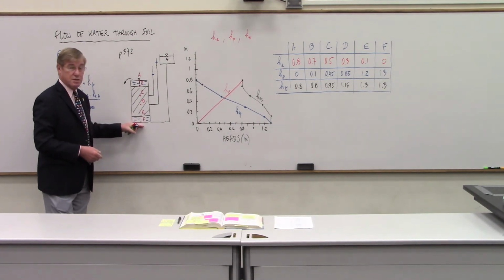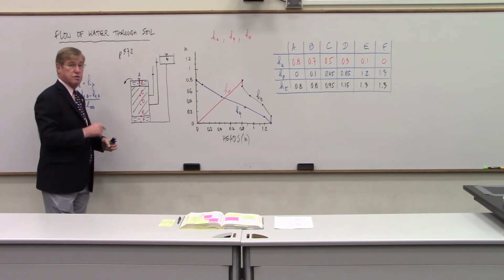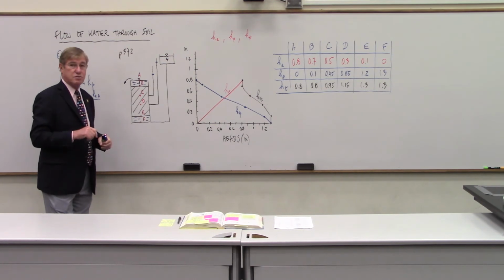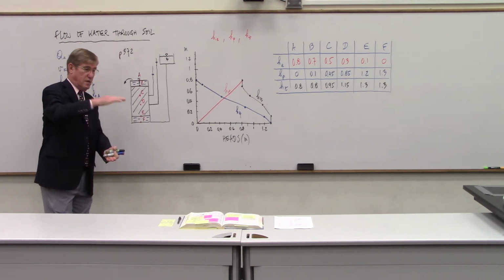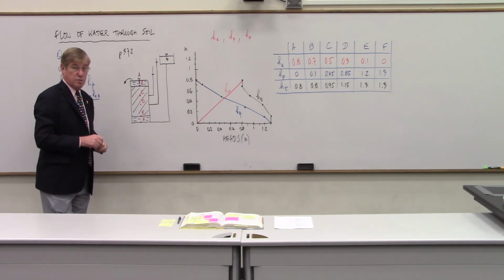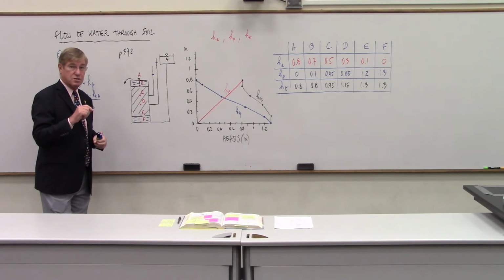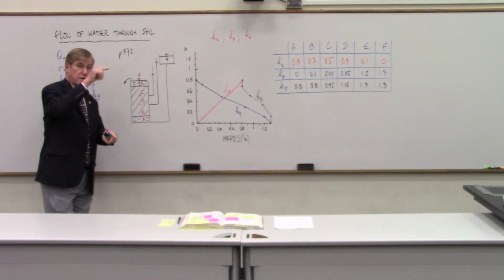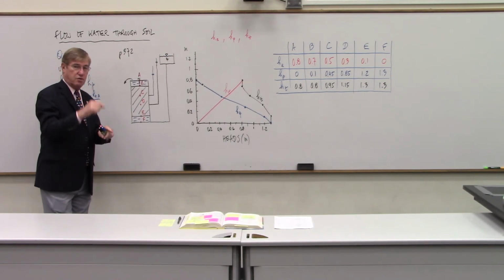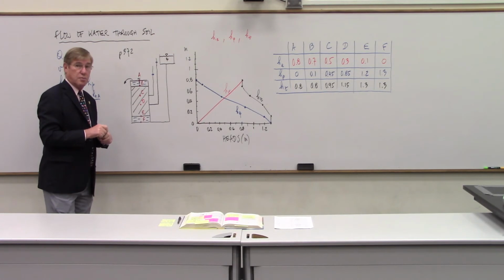This is not the case. You cannot apply this. Why? Because here the water is moving. And in the previous case where we had the soil and the groundwater level, everything was static. In that case, when it's static, you can go from the point to the groundwater level and say that's the height of water, and therefore I've got hydrostatic water pressure at the bottom.